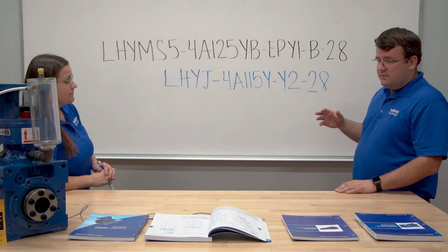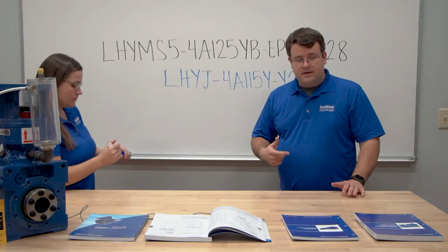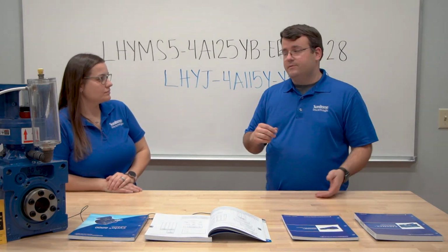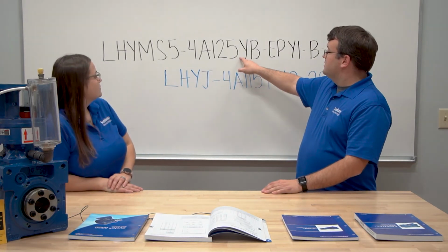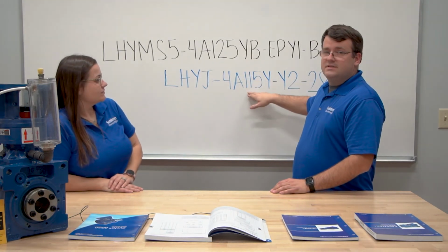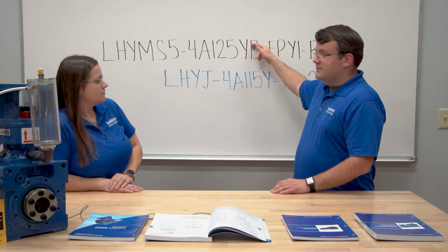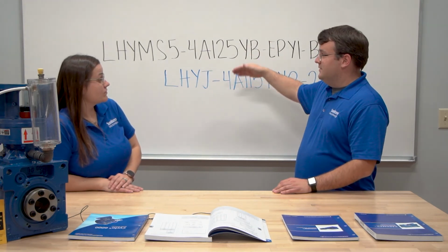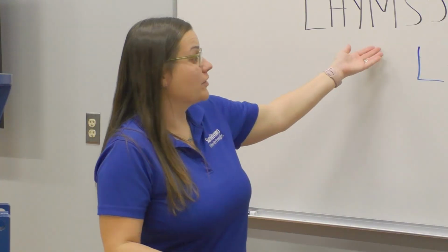The critical thing we want to mention, which we reiterated a lot with the special, is that if you do see an S, there is something different about it. It's not off the shelf. So if you originally had this and you happen to order this one, even if it was the same frame size, it might not be the same. You might not get the same life for whatever reason. There might be a different bearing. You also wouldn't be able to just plug our motor in.